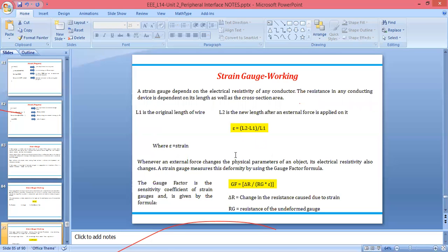It is a sensor used to measure the value of electrical resistance, which varies with changes in strain. Strain occurs whenever you give force or pressure and there is some deformation or change in displacement. And when we give that force, we call that force a stress.